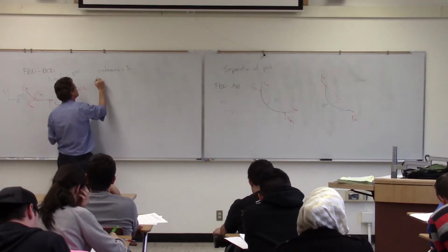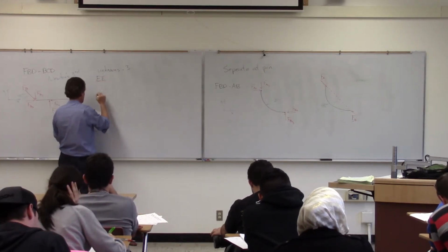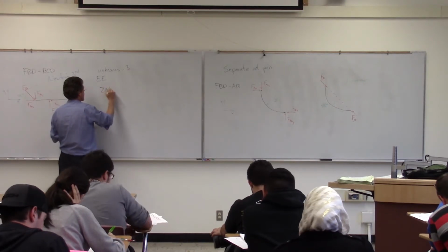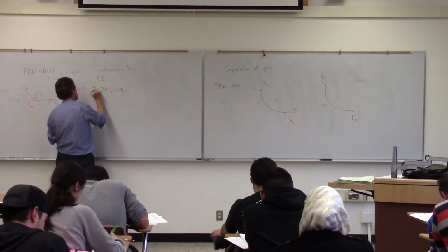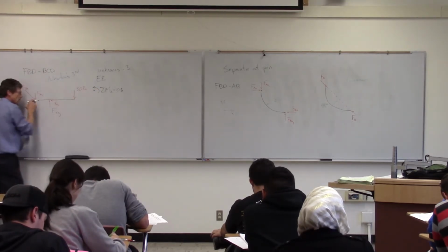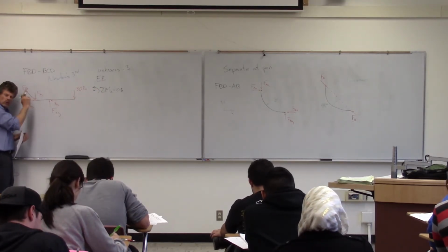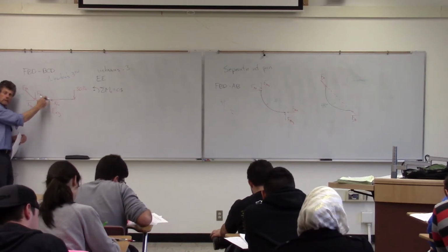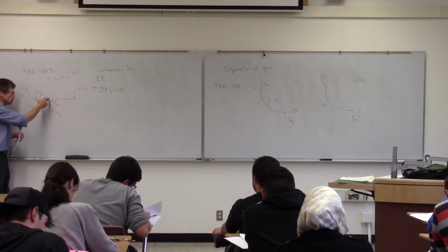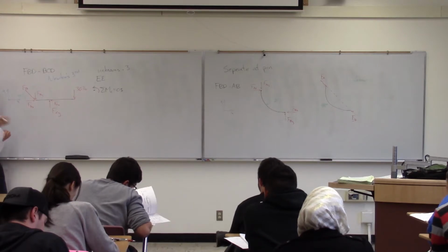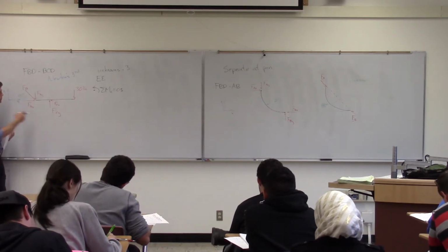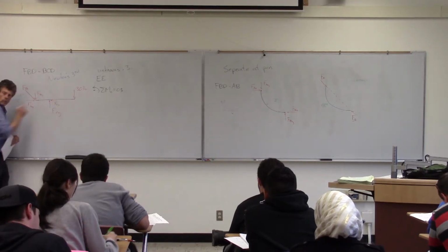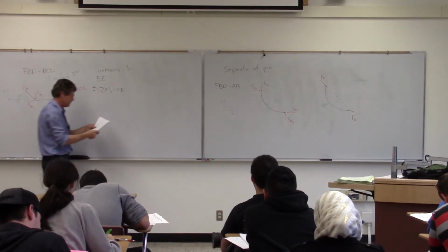So we'll go ahead. And again, since I've established this one, it's still an unknown, but it's only one unknown. If I go to C, I can save myself a little work here because I can eliminate the 2 unknowns there at C, the unknown force and unknown direction, leaving one unknown and one known.